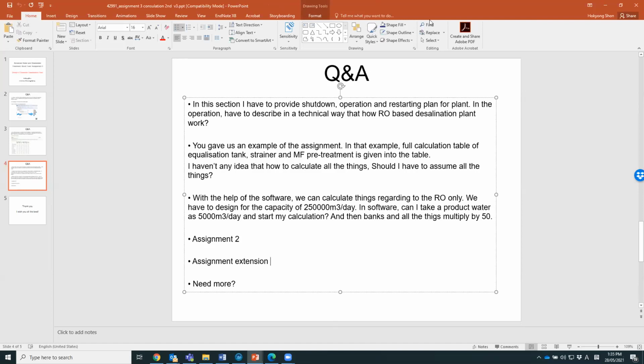Professor, I want to ask regarding the WAVE software. In this software, I take product water as 10,000 cubic meters per day, and in reverse osmosis, I have taken 66 pressure vessels in the first stage and 24 in the second stage. Elements per pressure vessel are 7 in the first stage, and I also take 7 in the second stage. I also added the scalant, but I still get a problem with BaSO4, which is greater than 100.